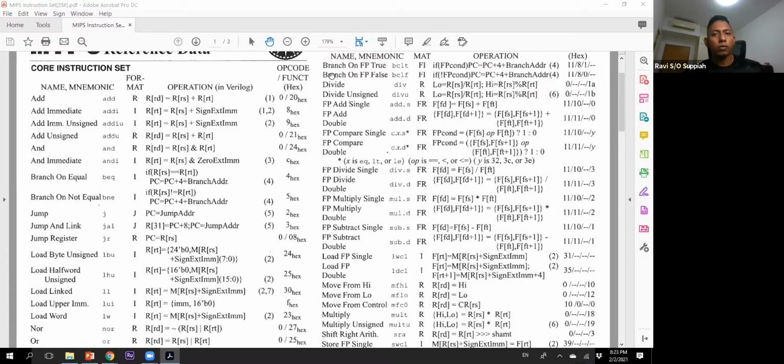In terms of another important piece of information for the instructions, you can also see that in the middle of this right hand column there is opcode and function. This is the way in which the processor is able to differentiate all these instructions. Like I mentioned just now, every instruction is 32-bit, but some bits are already reserved for certain reasons, and one of them is to tell the processor what this instruction is all about.